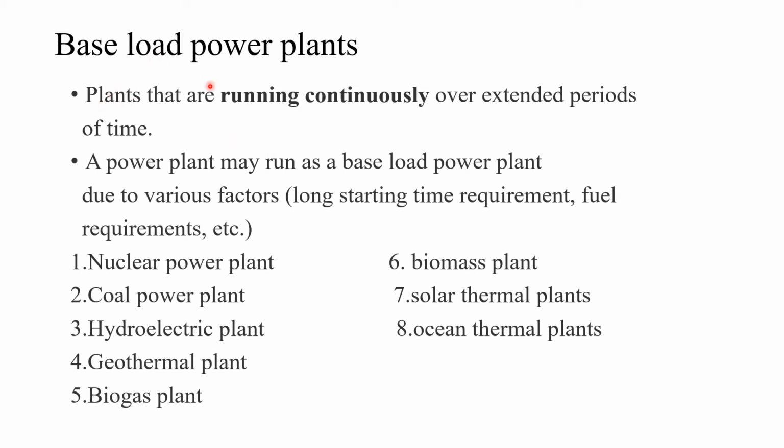The plants which run continuously over a period of time are base load power plants. Some power plants are categorized under this load and the others are peak load power plants, because some plants need a long time for starting, and there is less availability of fuel. These are the major reasons.